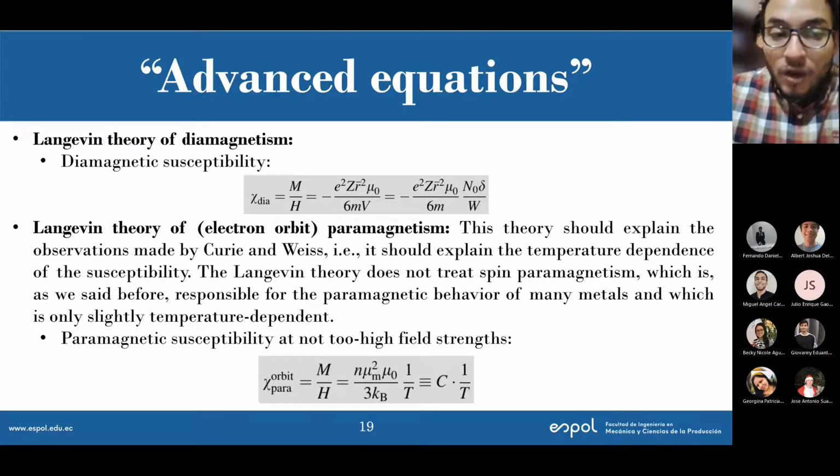And another interesting thing, you can see here there is no temperature term, and that's also in agreement with experimental values, because in diamagnetics we said susceptibility doesn't change with temperature. It changes, but very, very little, an extremely small change. That's why all the properties for diamagnetics are temperature independent. Okay, any question, guys?